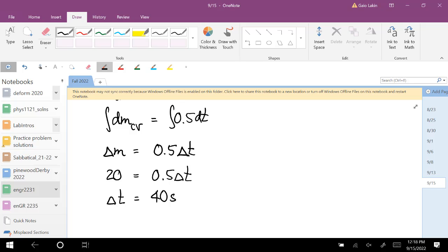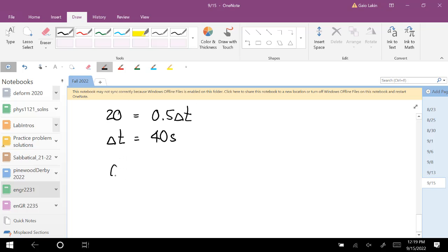And that's sort of like the simplest form of the way that you'll most often have to use this equation. You'll set it up in that differential form, and then you'll have to integrate to find like a certain change in mass. But usually, instead of being given mass flow rates, you'll be given stuff like the speed of the flow coming in. And sometimes you'll have to use a table to find properties, find the specific volume, stuff like that.